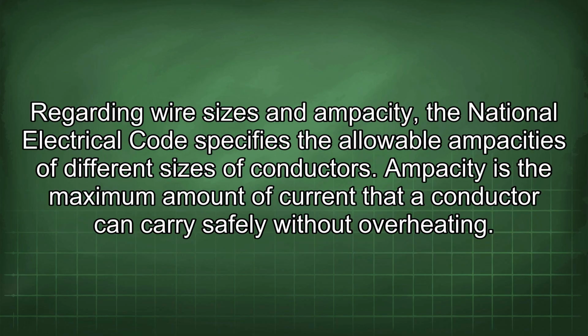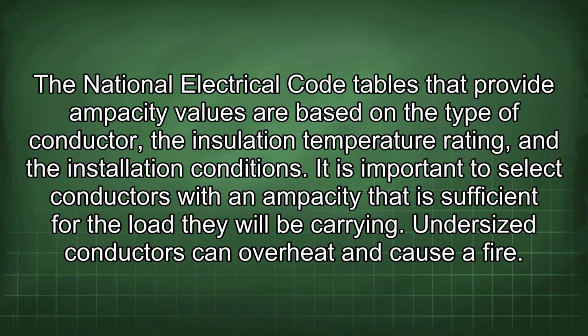Regarding wire sizes and ampacity, the National Electrical Code specifies the allowable ampacities of different sizes of conductors. Ampacity is the maximum amount of current that a conductor can carry safely without overheating. The National Electrical Code tables that provide ampacity values are based on the type of conductor, the insulation temperature rating, and the installation conditions. It is important to select conductors with an ampacity that is sufficient for the load they will be carrying. Undersized conductors can overheat and cause a fire.